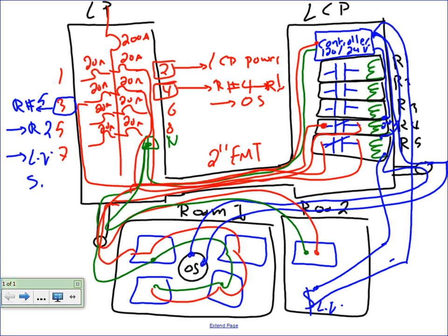So I showed you an example of an occupancy sensor, an example of a low voltage switch. Timers are the same. Any questions, guys? These are the most common ones. Low voltage switch. I will remind you the low voltage, the blue system, is a 24 volt system. This means a power limited technician in the state of Minnesota can install this system. What does that mean? Cheaper installation, safer installation, better control system.